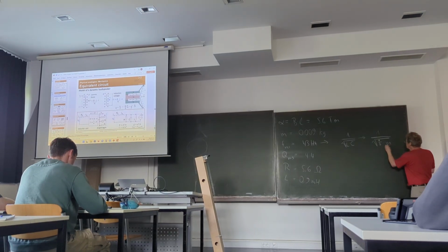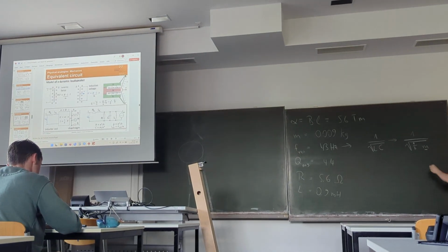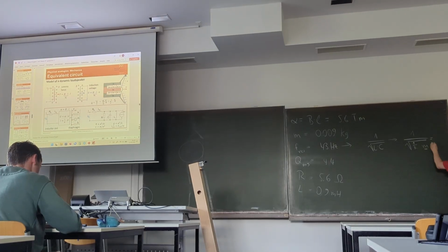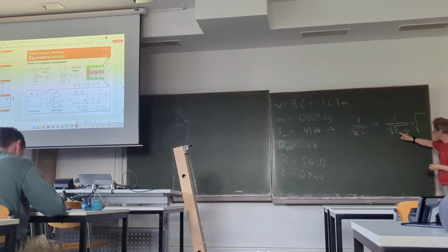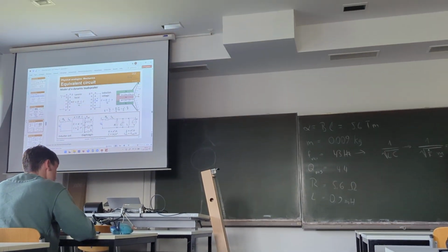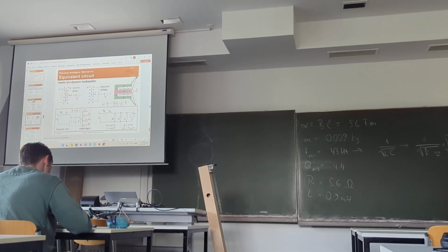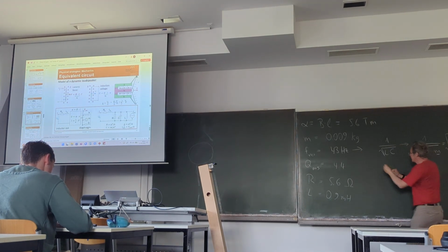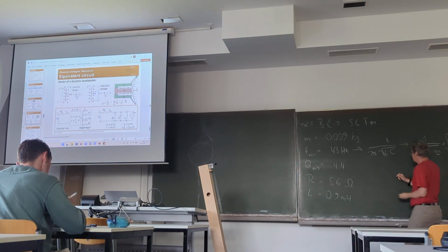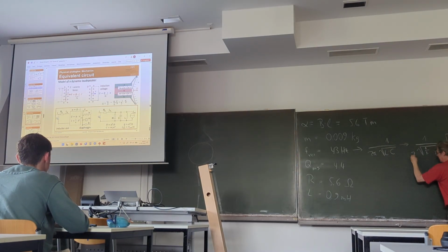And we already know the mass, and now we can determine this K. Let's put this in a nicer form here. This is a denominator of a denominator, so K on top, numerator, divided by m. That's better. So what you can do is take the resonant frequency, square it. I think I forgot something. I forgot a factor of 2 times pi. And of course here the same factor. Let's not forget that. 1 over 2 times pi multiplied with the square root.